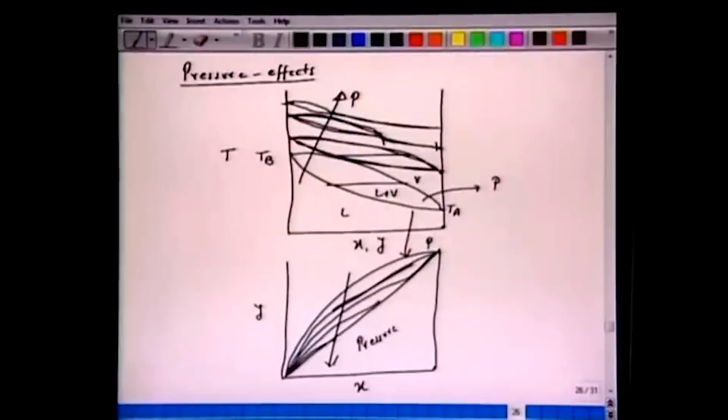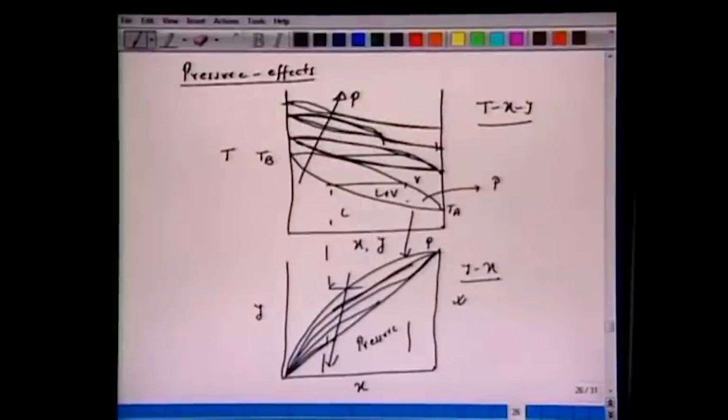Again, from the TXY diagram we have plotted, we can get the YX diagram, one can take the projections of Y and X, take X here, take Y here, go to the 45-degree line and connect with this X, etc. So one can do this. The idea is that here we have plotted the TXY diagram or YX diagram for changes of the pressure. At higher pressures, in general, most of the ideal solutions behave like this. The separation is less, the curve becomes narrower and narrower. Okay.